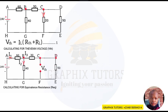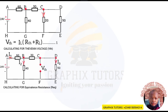So I3 will be the one flowing through the 5 ohm resistor. When we get our I3, we'll multiply it by 5. And when we multiply it by 5, we'll have a voltage drop, which will be the same as my VTH, because both of them are in parallel.